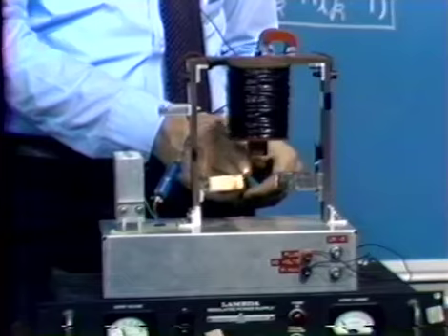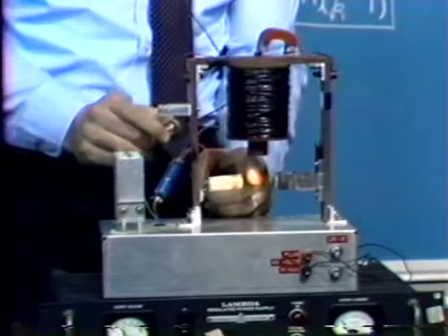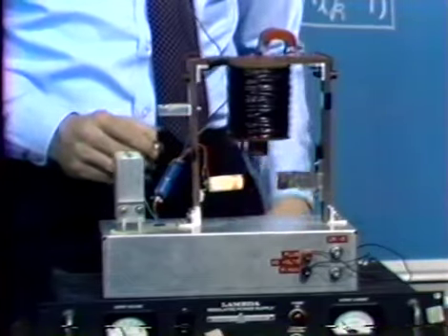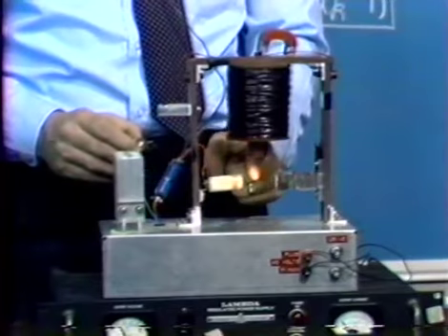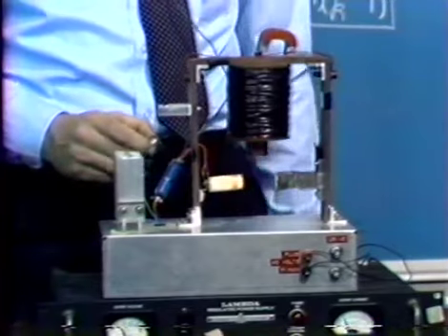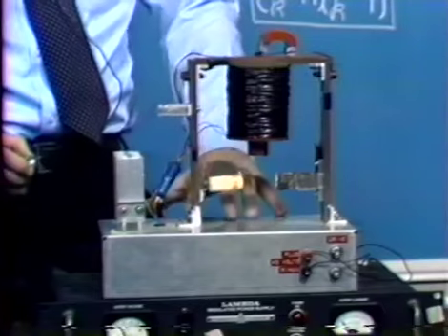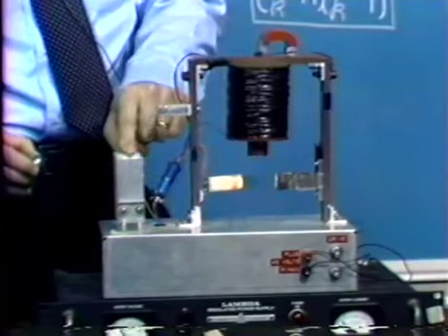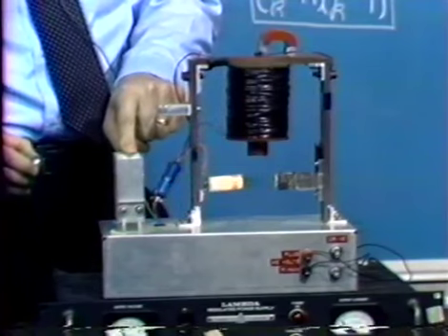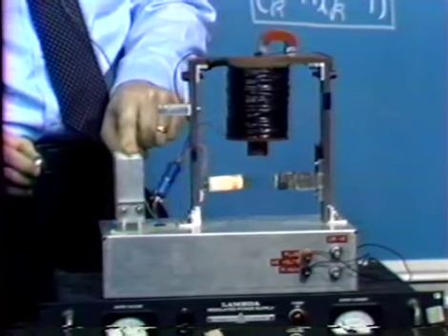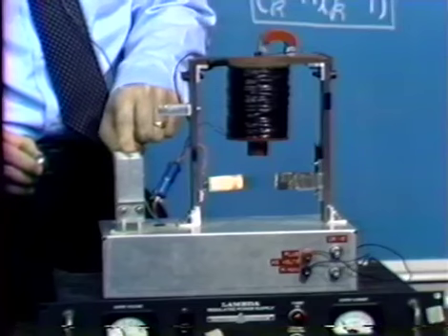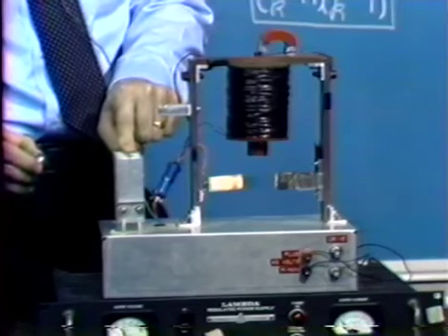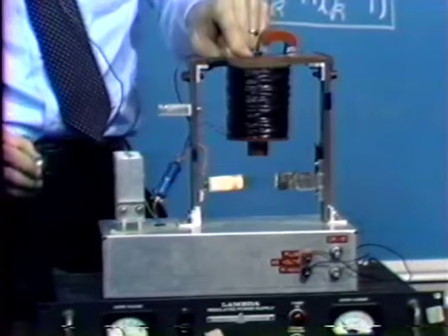The ball then casts a shadow on this linear photoresistor, and that gives us a method for measuring the position of the ball. And there's some electronics inside the chassis which drives a power amplifier, a power transistor on this heat sink. The output from the power transistor, the collector current of the power transistor, actually drives the electromagnet.